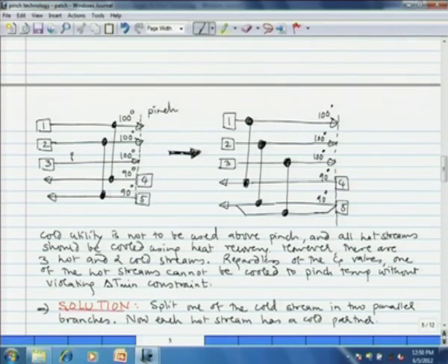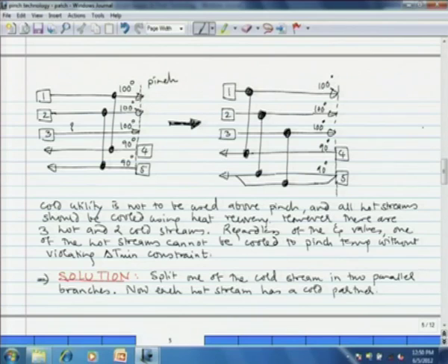If we follow the tick-off heuristic, then we can place 2 matches which will tick off either hot or cold streams, but we shall still be left with 1 hot stream for which there is no matching cold stream. In this case, stream 3 has no cold partner. How can we make a match for stream 3?